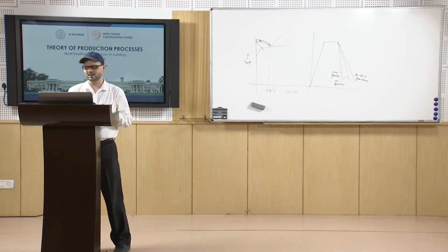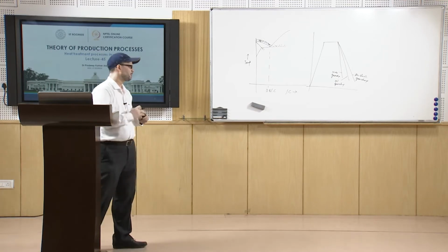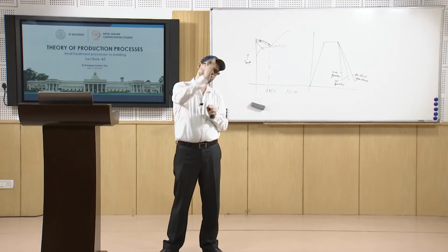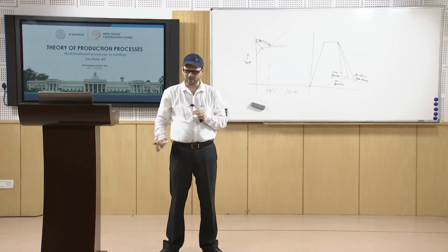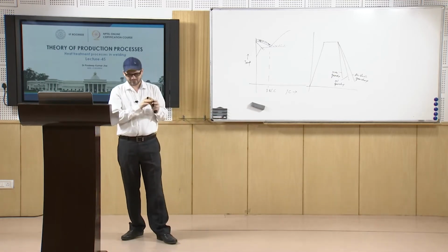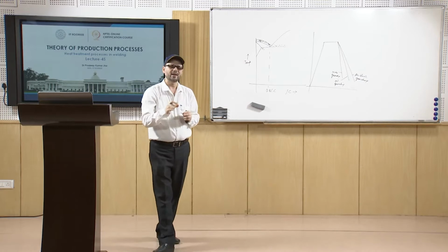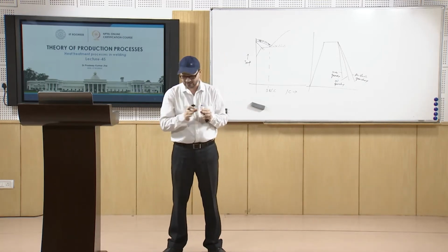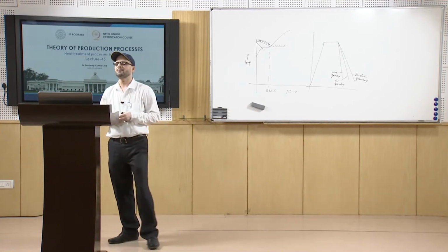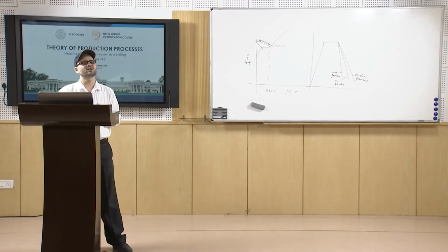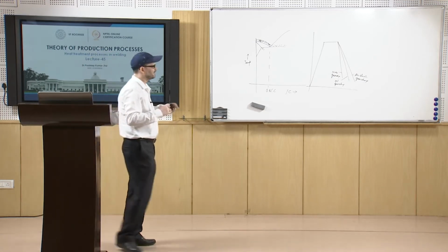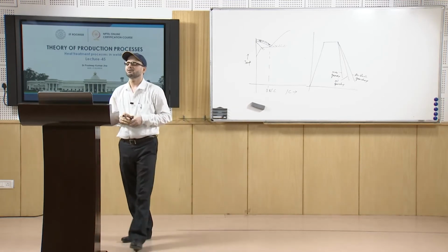Normally in industries, once you go for quenching, you heat, hold for some time, and quickly quench it in a quenching medium. Then it is followed by the tempering treatment. Again you are heating to a lower temperature, holding for some time, and then free cooling in the air to give you the tempering stage, and that is known as the quench temper cycle.